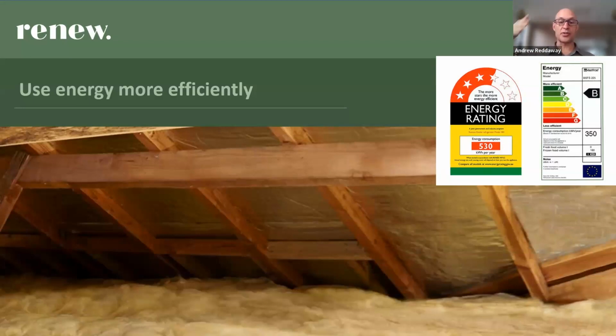There's also some foil underneath the roofing, which especially in summer helps to resist how much heat is radiating down from the roof. So things like that, draught-proofing, efficient appliances. We have whole webinars on all of that stuff. Getting off gas, of course. All of those basics do make a lot of sense, and especially some of the things like draught-proofing. They're so cost effective. The payback time is fantastic.